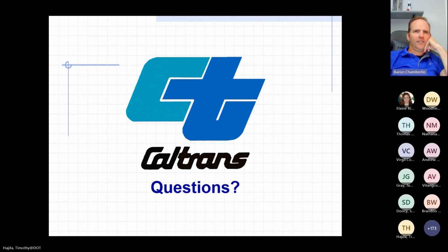So another question I see is why use mobile LiDAR over UAS LiDAR? I can take that one. Tim, do you want to handle that one? Yeah, with our mobile scanner, we can achieve design grade accuracy. We're not able to, I should say, specify vertical accuracy. The UAS LiDAR is not to that level of vertical accuracy for our design purposes. And another reason, which Abe mentioned, is flying over roads.